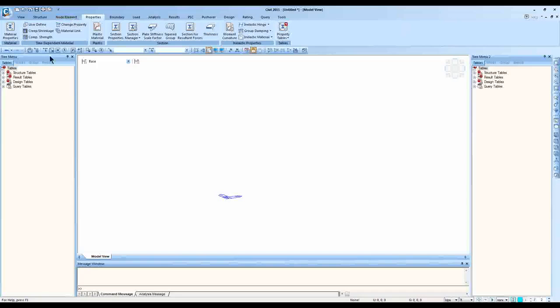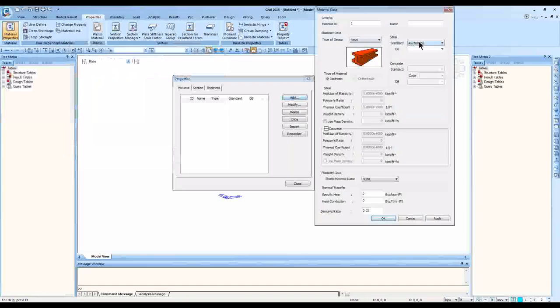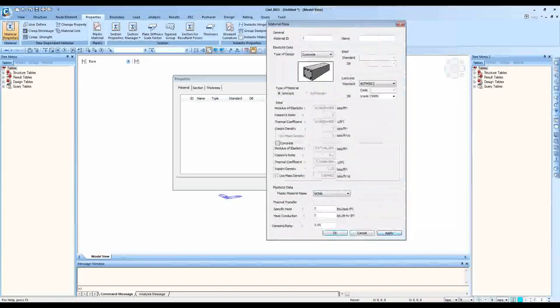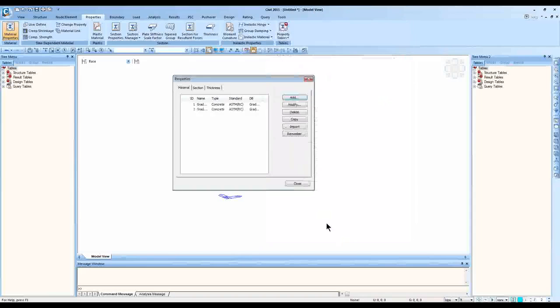Okay, so what I'm going to do from now on, I'm going to quickly set up a straight line girder model so that I can help understanding how to use construction stage function in Midas Civil. I'm going to define 2 materials real quick, one for the girder portion and the other one for the deck portion. Girder C9000 concrete was for the girder portion, and 4500 was for the deck portion. So I defined them in ASTM-RC material database.